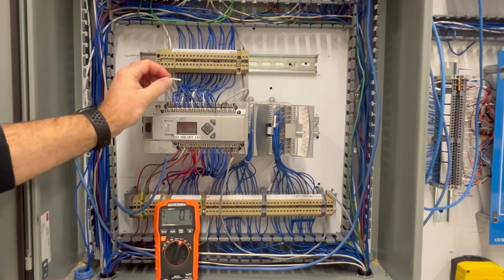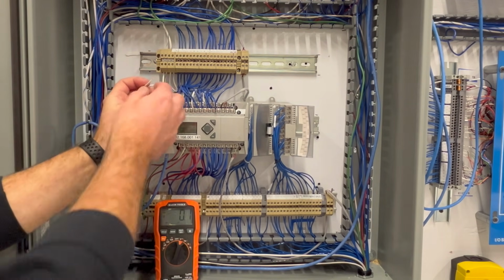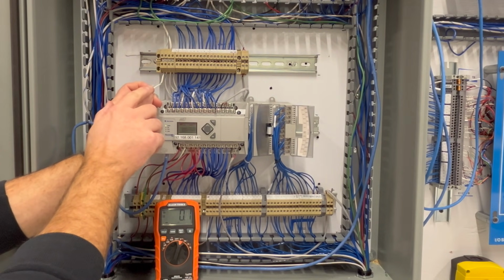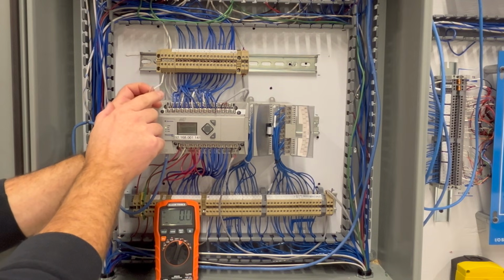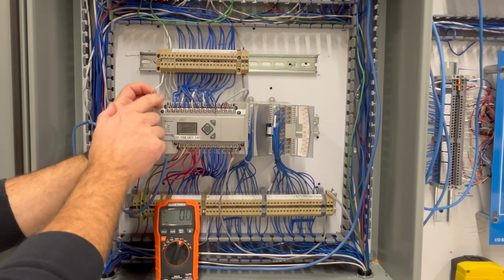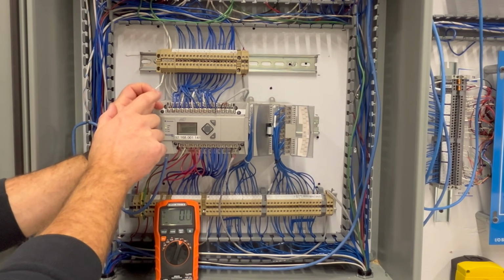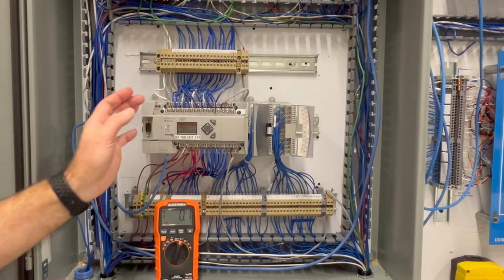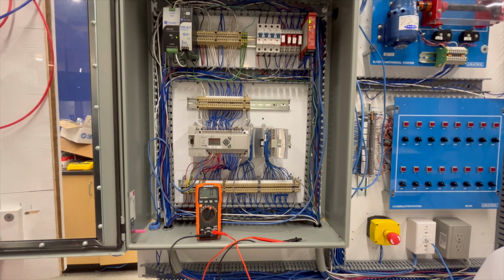As I tugged this, you can see this popped right out. And somebody who stripped this, they did not do a good job, or something else happened. Maybe they stripped it too far. They cut it and they didn't realize that everything was in, but it might be too hard to see, but this is pinched right here. So now I know what the problem is. I can come in here and fix it.